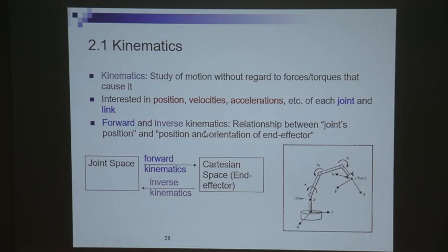So the inverse kinematics is a lot harder. When you turn the joint angles and the links are rigidly attached, you multiply a series of matrices, and then you get the end effector position. But when you're given a position and you try to calculate backward, you may find that it's not so straightforward. In some cases, you may have no solutions. You can't reach that point. And in some cases, you have multiple solutions, and multiple solutions may not necessarily be a good thing.